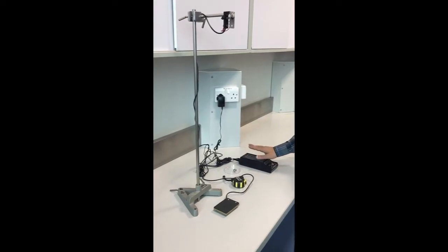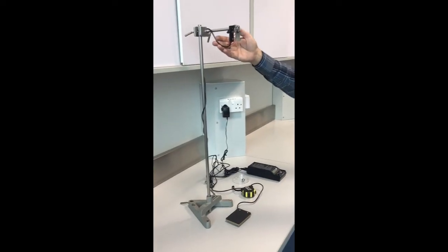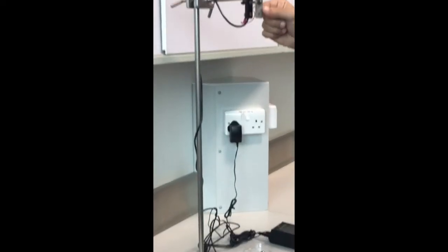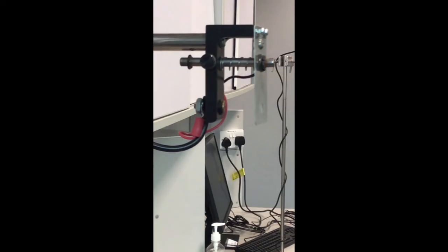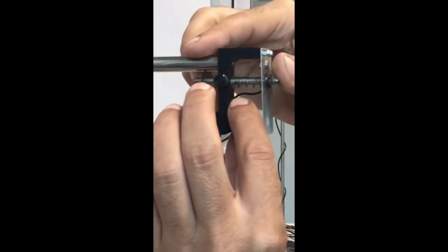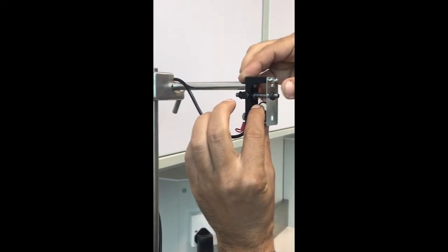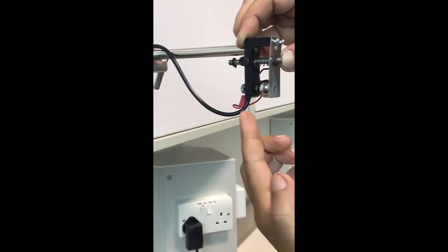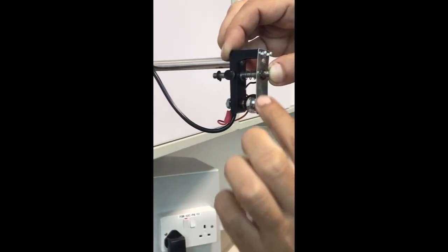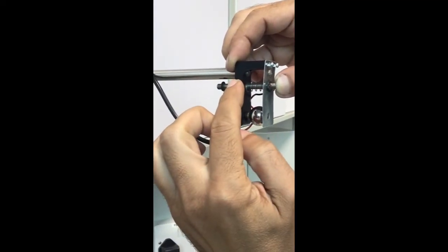Now, in order for this device to work correctly, here we have two connections. As you can see, there are some wires. One connection on this plate and the other one on this brass screw right here. Okay. So when you insert your ball right here, this is how you will fix it in place. You will press on the shaft right here. Now the ball is held by the pressure of this plate, and then I want to hold it in place, so I'm going to tighten this lock.